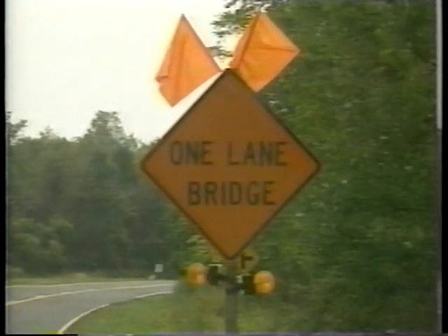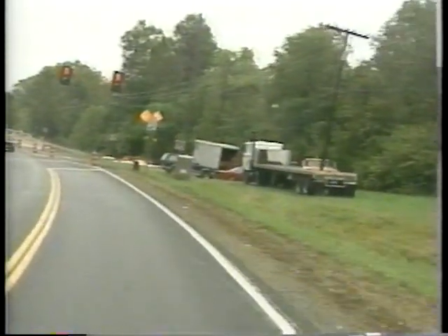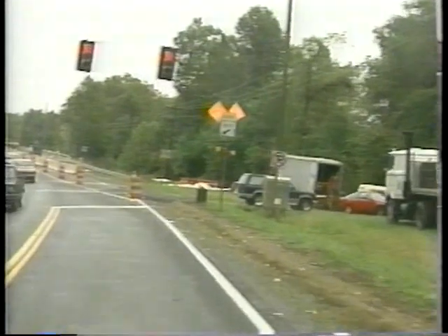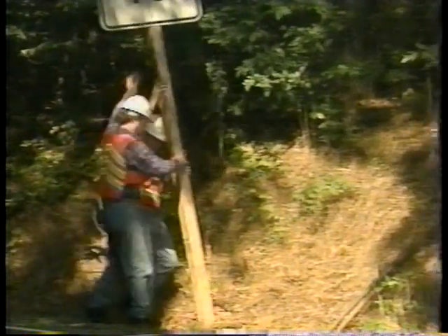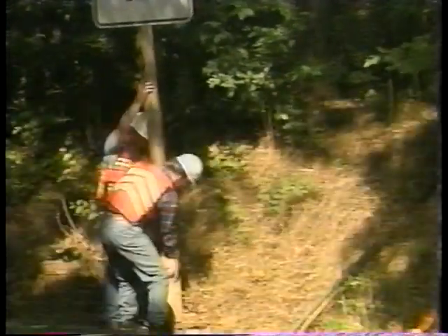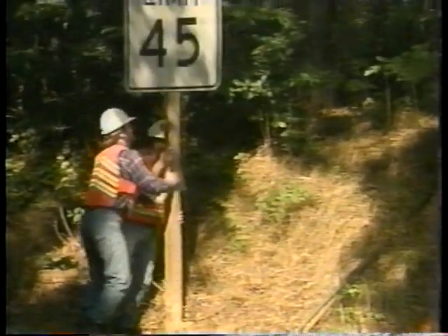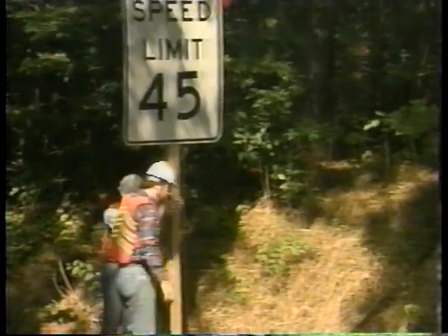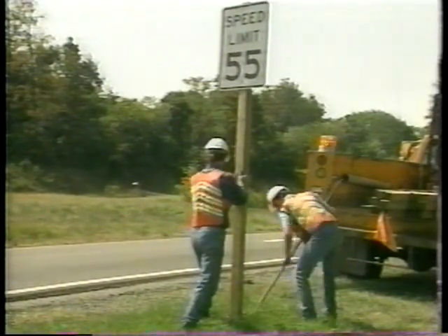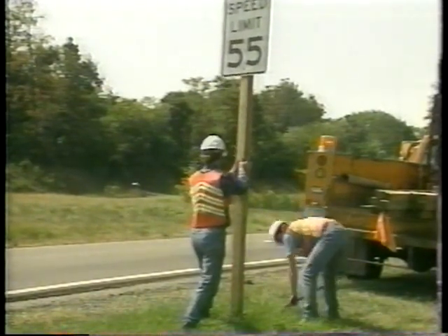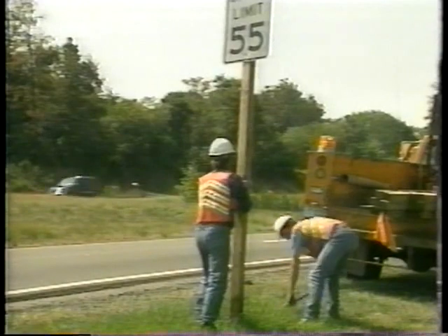Provide clear and positive guidance for drivers in the approach area and as they go through the construction and maintenance work area. To do this, first install temporary devices to maintain guidance while permanent signs are missing. This will protect workers during the operation. Then, remove any existing devices that will be inappropriate once there is a work zone, because they might confuse or contradict work zone devices.